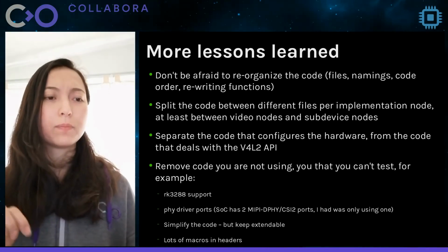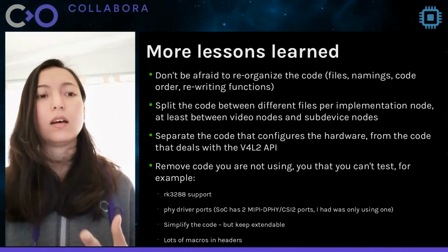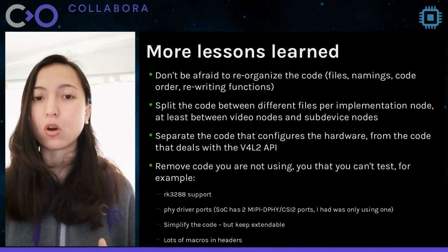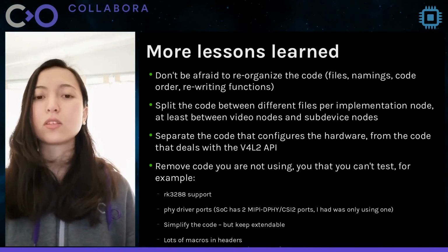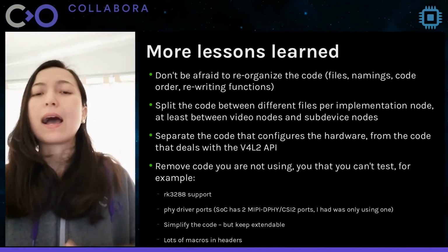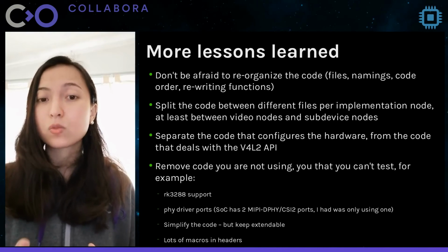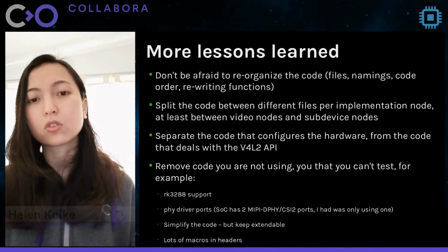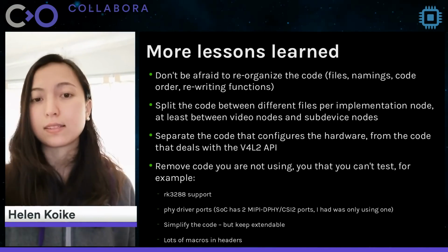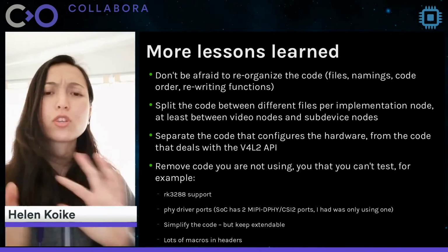Also, the driver DPHY part had support for all the MIPI DPHY CSI ports, and it also had support for the DSI port. And I was not using this one, and most of the hardware that I saw, most of the boards, were also using just a single port. So just remove everything.